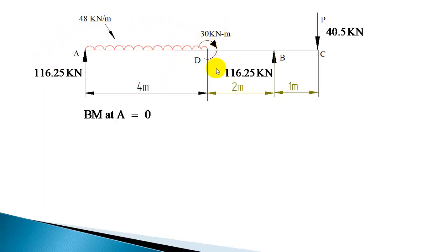Immediately right of that point you get the same moment summation for these forces, since you are only moving an infinitesimally small distance. But when you take the right of that point, you have to include the couple. So left of that point without the couple, and right taking the couple. You can calculate the bending moment like that.